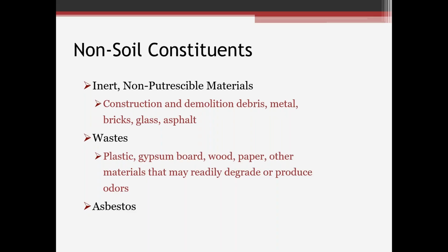But generally when you remove soil from New York State, it is considered a solid waste until you can prove that it meets some beneficial use determination. So basically waste being something not intended for its original purpose. So as you excavate it, if you do have a beneficial use for it, great. We don't have to fill up a landfill with that, but if you are mixing in these types of materials, you're looking at a disposal condition on that.